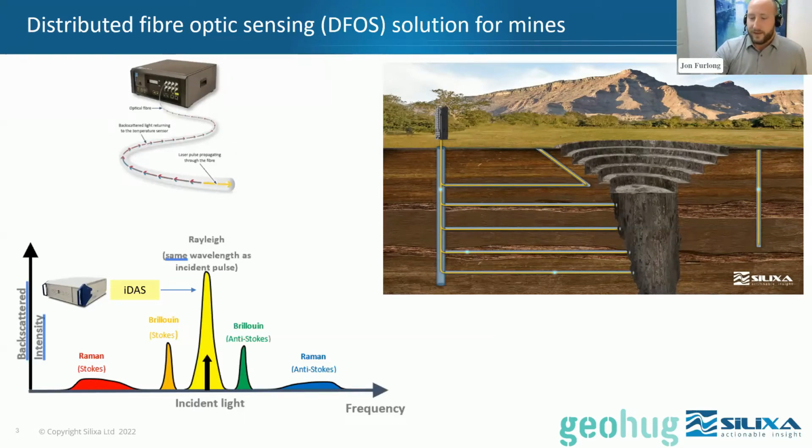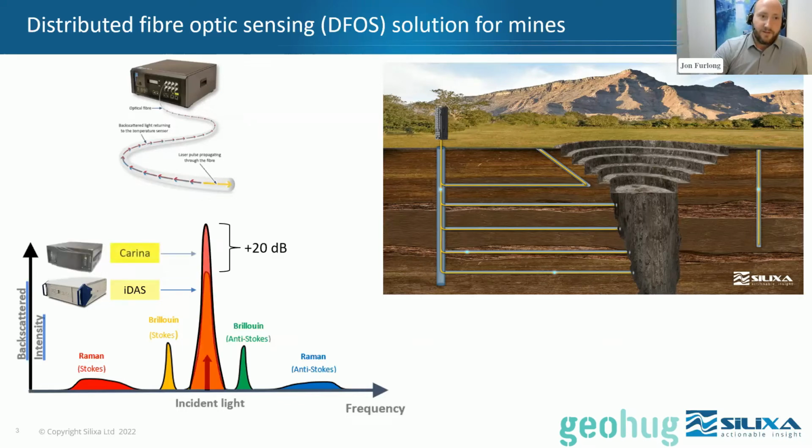What was normally difficult to do to measure acoustics, now we've been able to lower our noise floor and see a lot more. And we can also use engineered fibers and finely tuned systems to further decrease our noise floor. When we measure a backscatter response with Rayleigh backscattering, we need a small strain rate in the fiber that creates a reflection that we measure at an interrogator. But by engineering the fiber, we can create signal with a smaller amount of strain on the fiber to create a backscatter response, and that in effect just lowers the noise floor.